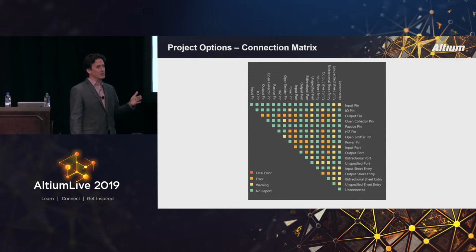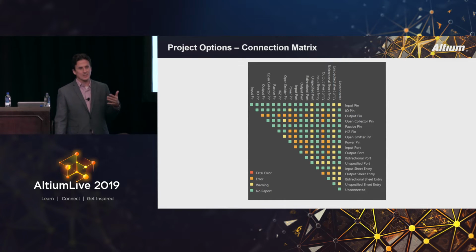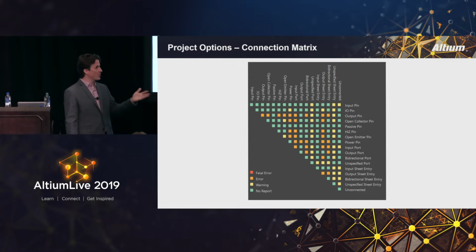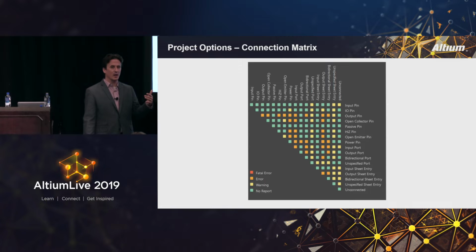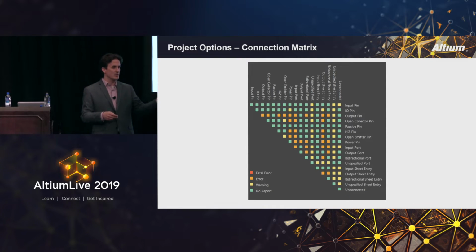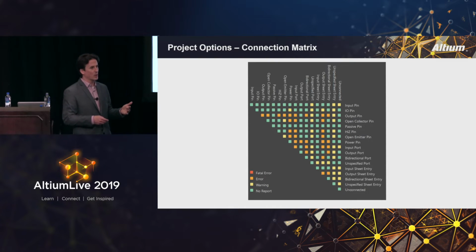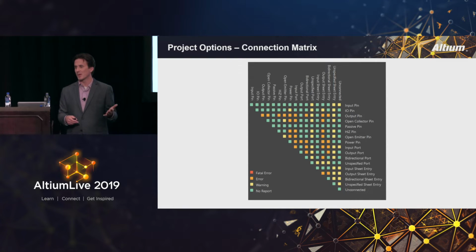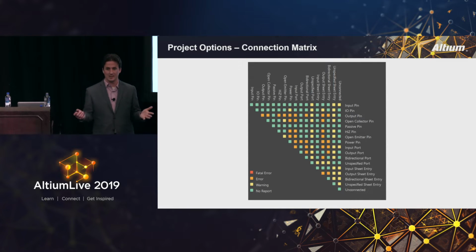I'll just say that there are some tools, the schematic symbol wizard, and some other tools for copying schematic symbols or setting up schematic symbols from Excel sheets that really enable you to do this quickly. And I find that it's not that much more work to set up the electrical type of a pin on my schematic. And again, it's something that has saved me.